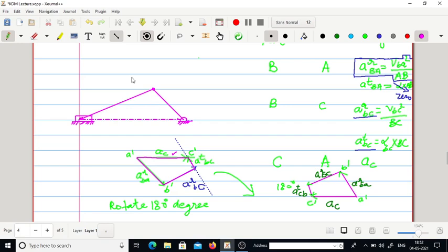This is fixed. So according to Klein's, what would be the velocity diagram? To draw the velocity diagram, draw a line perpendicular to this link, then extend this line wherever these two will meet. That will give us a point. For example, that point is P, this point was B, this point was A, and this point was C. So this is the velocity diagram. Now in order to draw the acceleration diagram, according to Klein's method, we need to draw two circles.